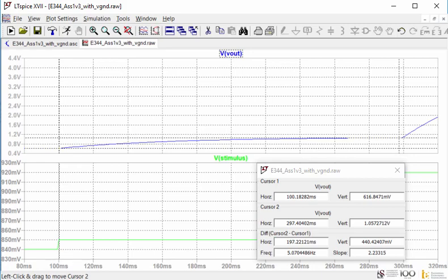So I have 1 degree is 10 millivolts times 45, and that is, well, 47 was my gain, sorry. So it's more or less 470 millivolts that I'm expecting the jump to be, and I'm getting 440. I'm obviously not a perfect circuit. I'm getting 440, but you can see that it's settled there.